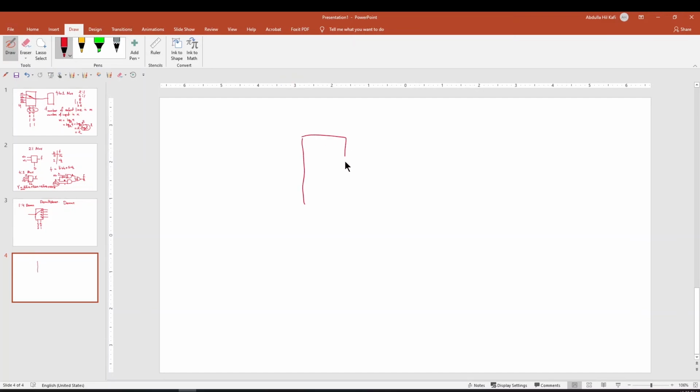So now we will design a 1 to 2 line demux. So we have one input line and two output lines, y0 and y1, and we can make it with one selection pin, which is S. If you see the truth table, the input is W, and S is the selection, but now we have multiple outputs, y0 and y1.